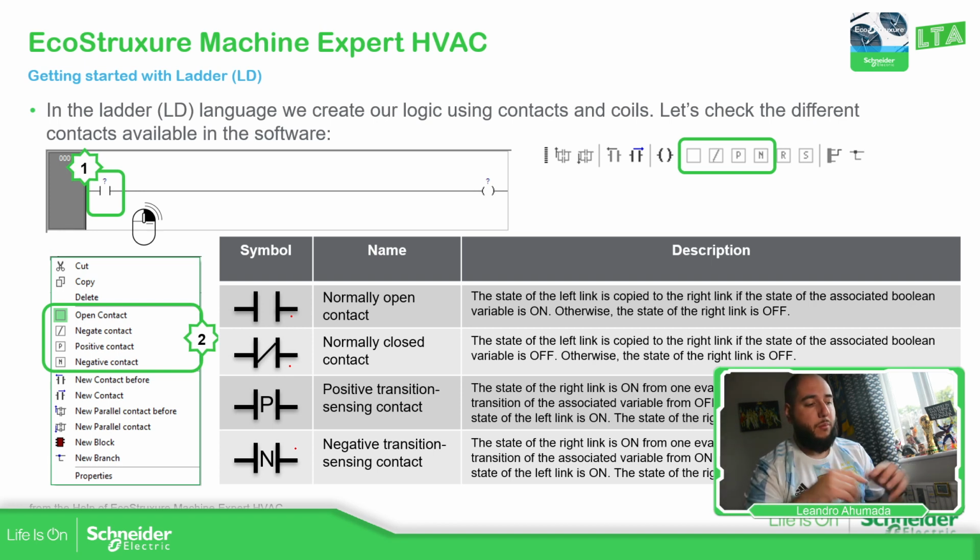So when, for example, you are making a counter for an input, and instead of using the actual contact, because in every cycle of the controller we're going to add something, you can use this one. It's just like a trigger, just a pulse. So you can use that one instead of using another function block for the trigger.